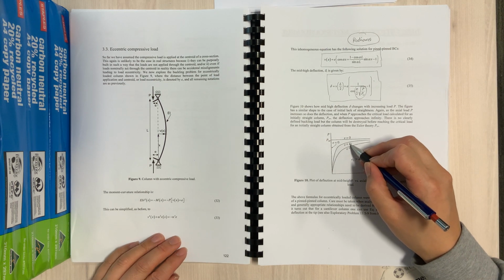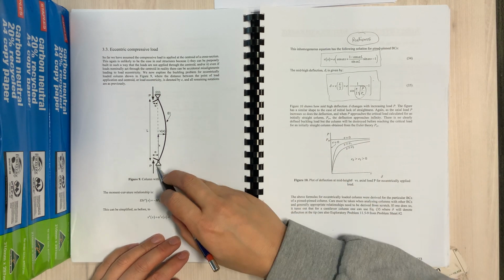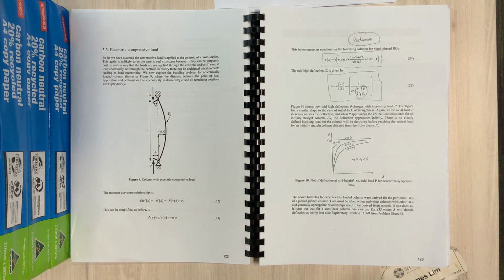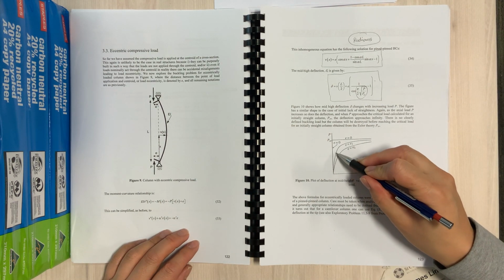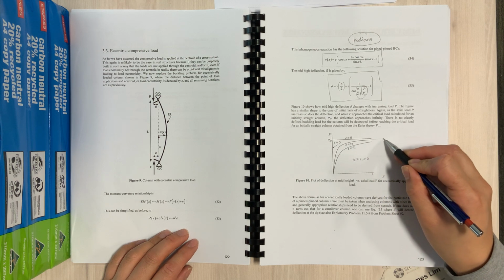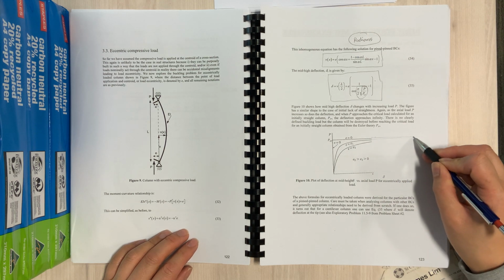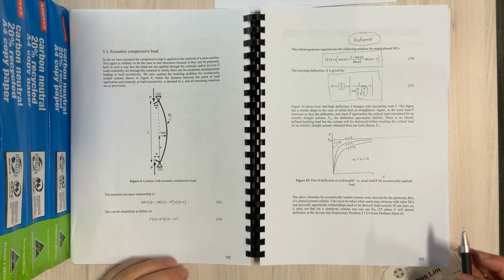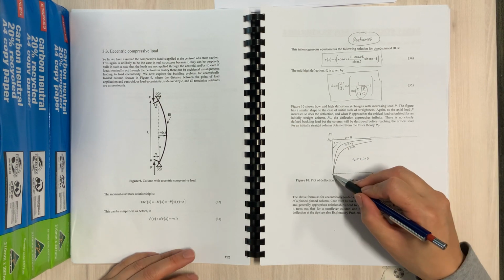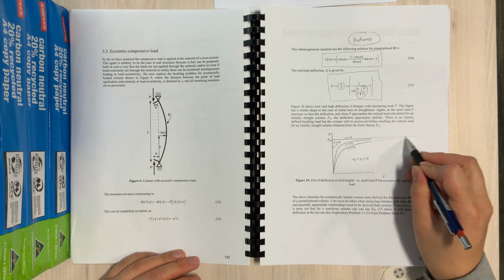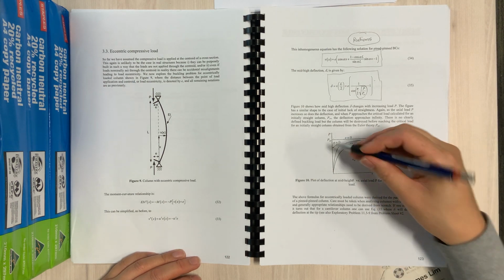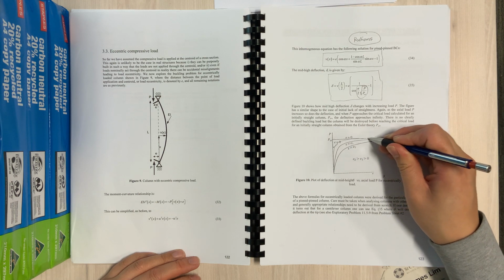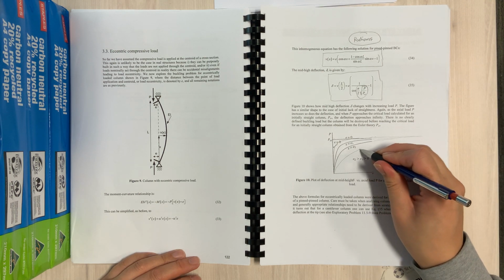If the eccentricity is E1, which is not a very big value, then the curve is going to be more rounded, and of course all of these would approach that value in the end, since a column can't take more load than PCR. If the eccentricity was larger, it would be like that, and so on. So if you had a smaller eccentricity, it would look like that, and then if you had a larger eccentricity, it would look like that.